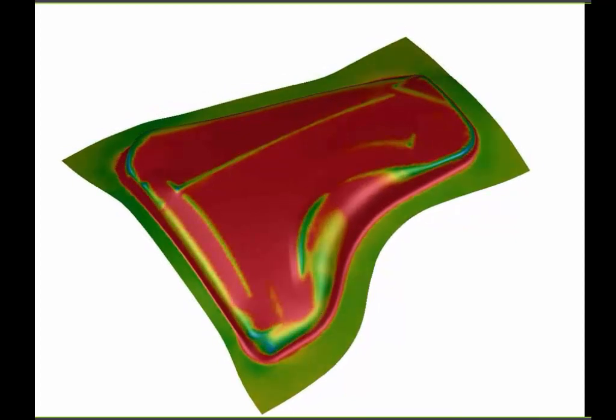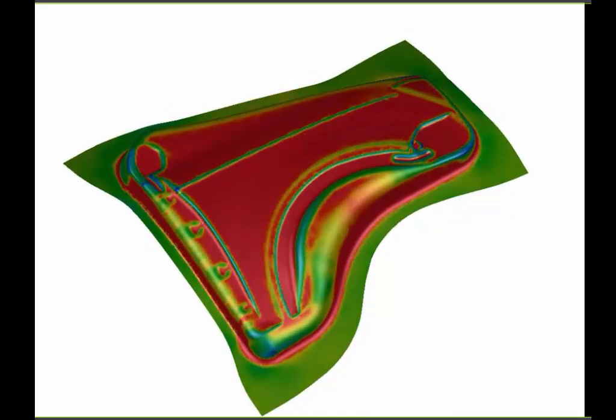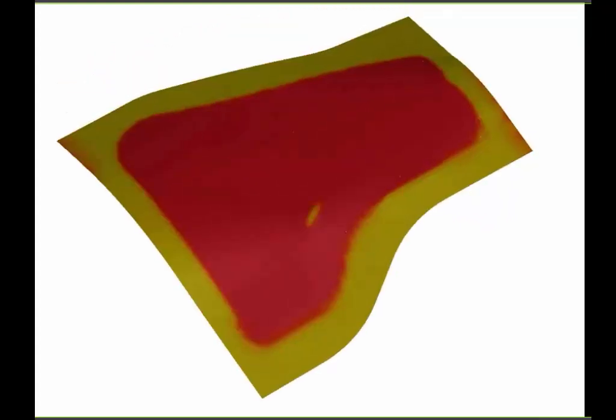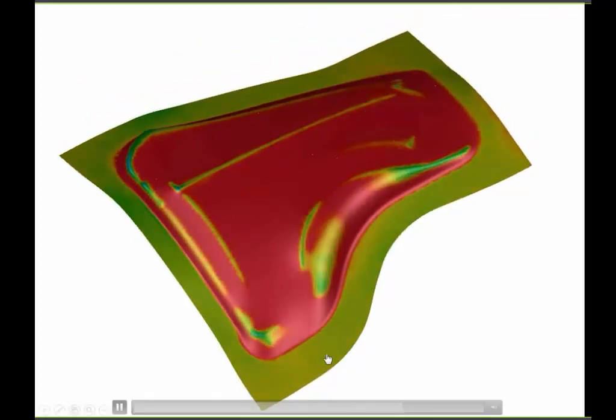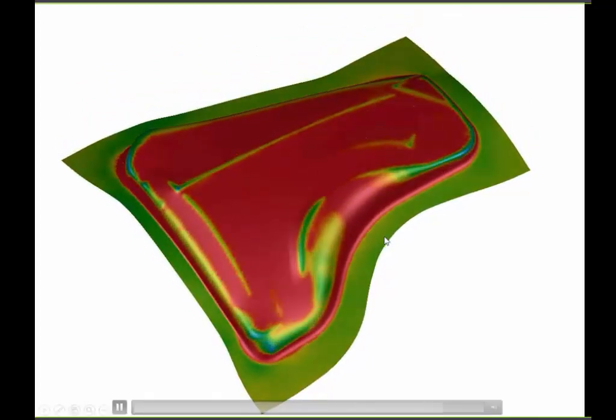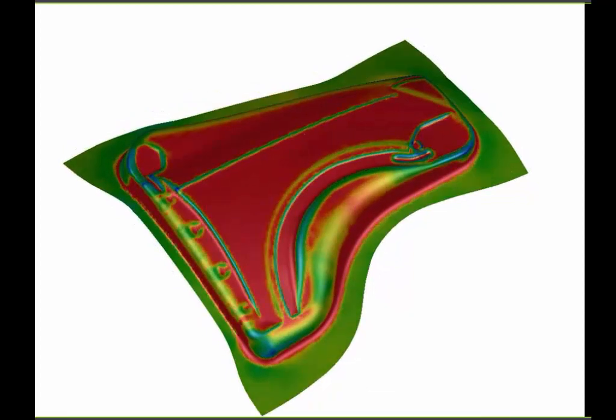And you also see that in high pressure regimes, so in die radii, for example, we will find lower friction coefficients. So high pressures, high strains in a material result in lower friction coefficients. And also underneath the blank holder, for example, we find lower contact pressures resulting in somewhat higher friction coefficients.